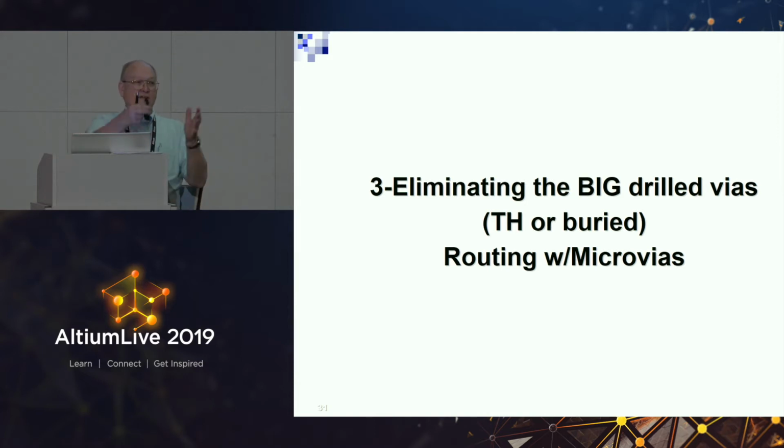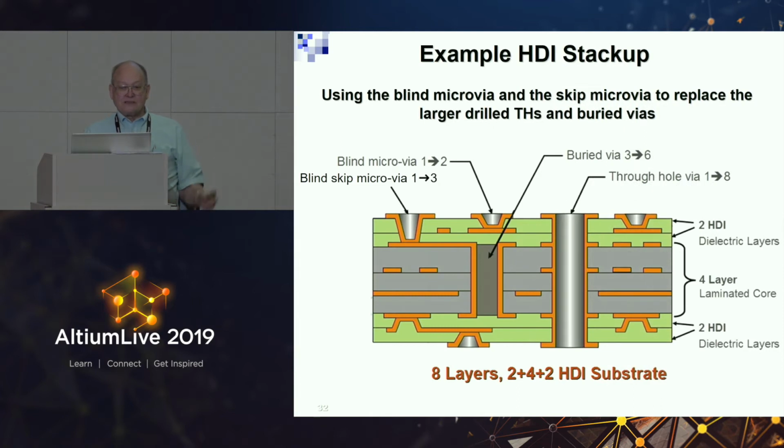So that's why you have to unlearn multi-layer techniques, because now you're over here in a realm called HDI, and the rules are different. But nobody ever told you that the rules are different, and the fabrication is different. And so this one is elimination of big holes. And so what I mean is, get rid of that big guy and replace him with the little one. That's a priority in concept. And the problem is that, in a multi-layer, you only have the big holes.